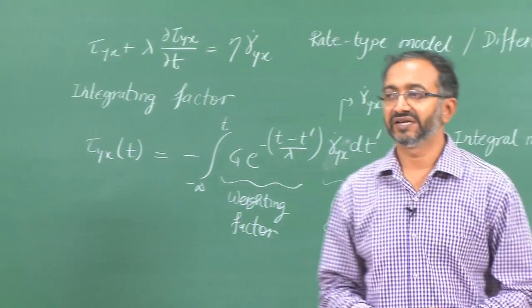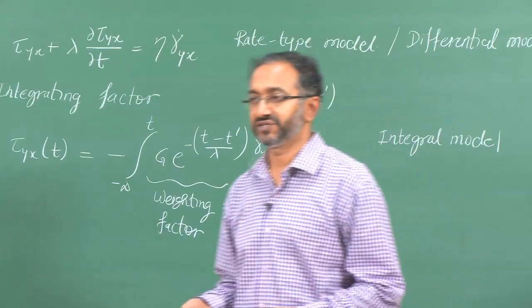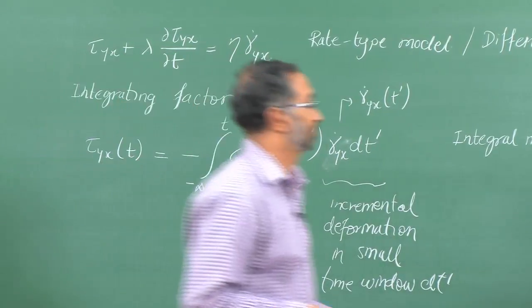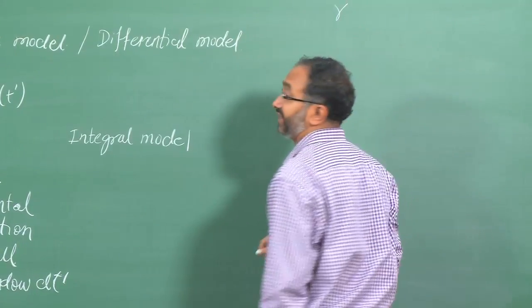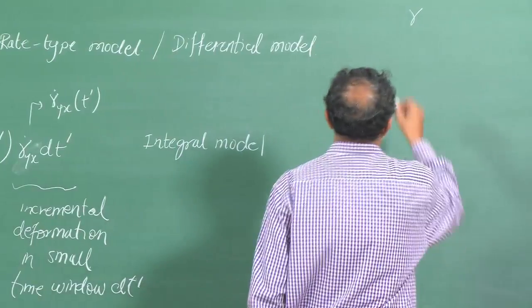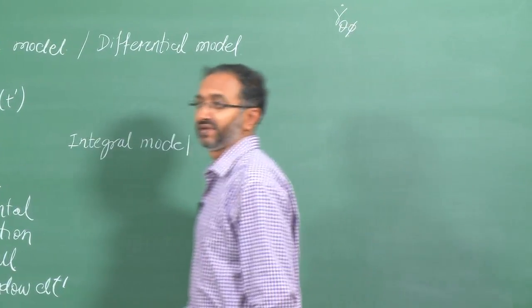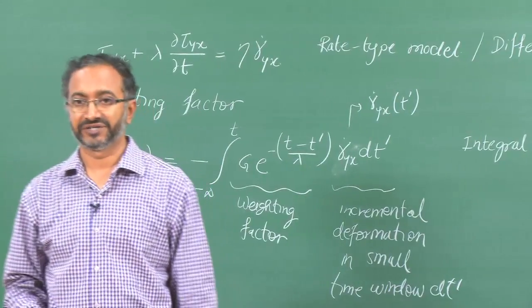So in case of oscillatory shear, we impose either a strain or a strain rate or a stress which is a sinusoidal function. So in general you could have any of the different types of strains, and in this case I have used the notation which is valid for a cone and plate geometry, which is used quite often for rheometry.